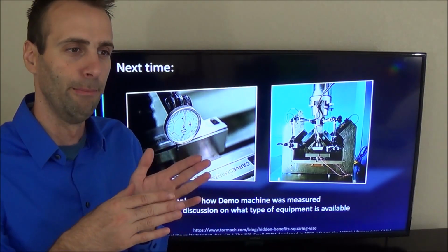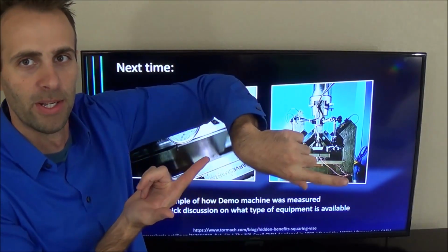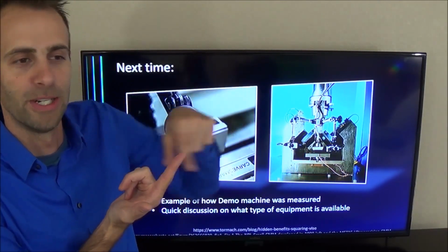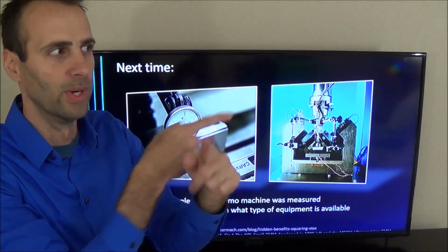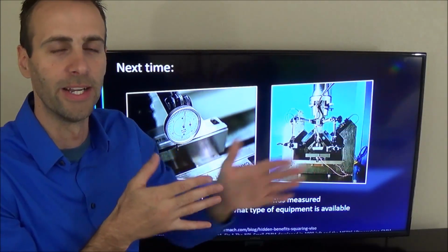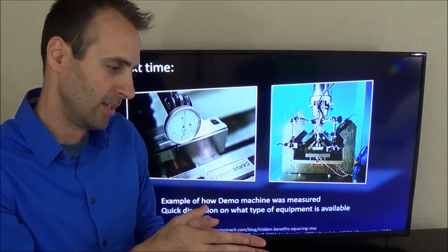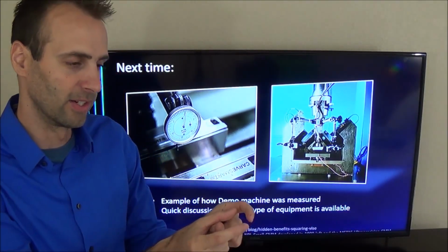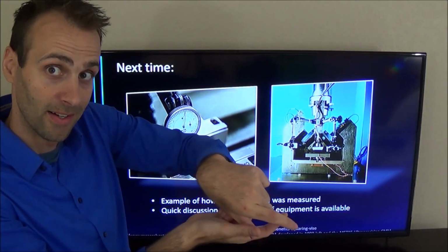If you have a bent straight edge, for example, if I flip the straight edge around and measure it again, now my errors are exactly opposite of the way I measured it before. So they negate into a perfect straight edge, right? All of a sudden my $5,000 zero-grade tiny little gauge block that's almost perfect just turned perfect.